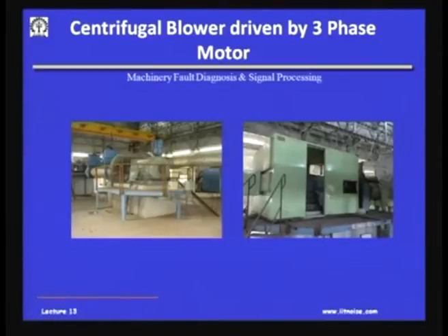Okay. Now, in this single room, because there are 5 blowers, what happens if one of them is running at a speed a little less, even 1 RPM or a few RPMs? The frequency of these machines will be different, and because they are close by, the phenomenon of beating is going to occur.